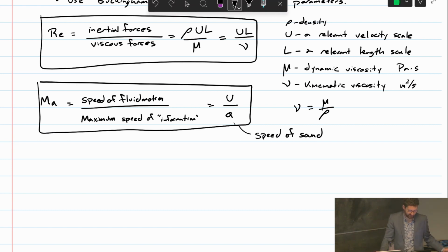So the maximum speed, for example, you get a shock wave at Mach 1. And that's because, say the plane is traveling and starting to speed up, the fluid ahead of the plane has enough time to move out of the way. It has enough time to receive the information that the plane is coming. But when you go faster than the speed of sound, the fluid ahead of the plane hasn't actually received the information that the plane is coming yet, so it's shocked, and then you get this accumulation of fluid particles right after the shock, and they continue to shock the other fluid particles. That's basically how a shock wave works.